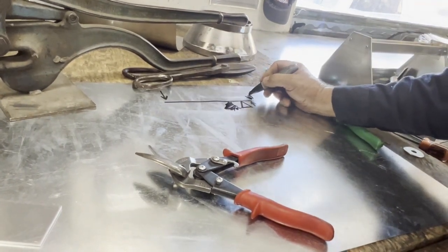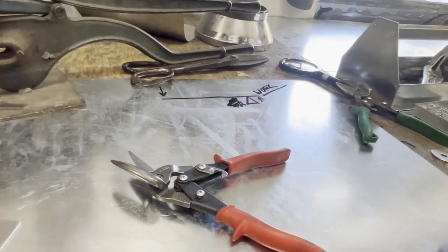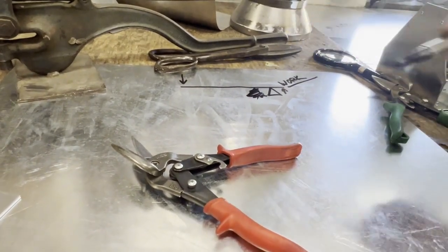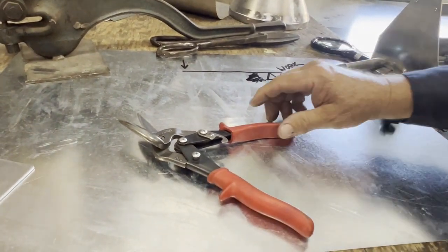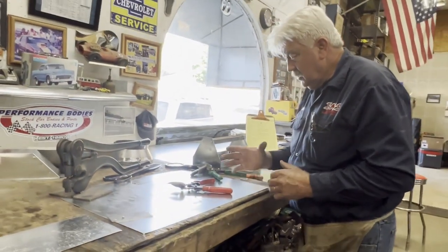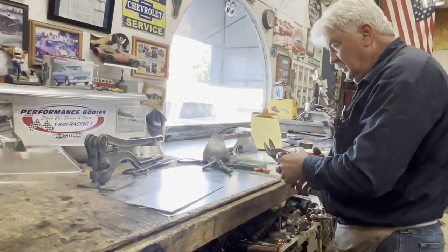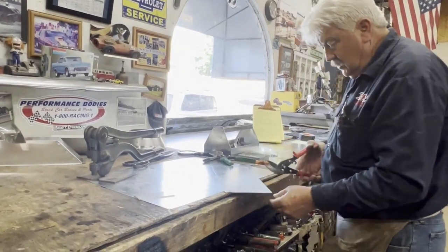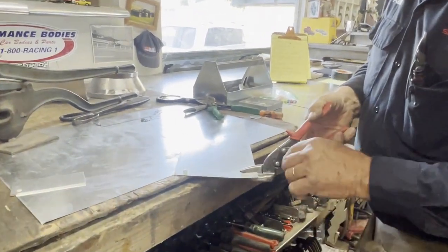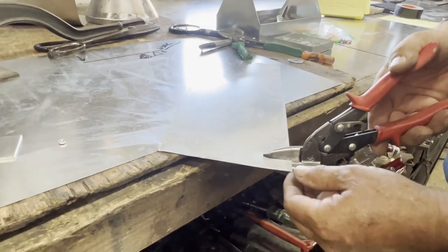The work is the metal. So this additional leverage allows us to do more work. As the metals get thicker, they get a little harder to cut. One of the things that we have to be aware of is that whenever we're cutting, whenever we're shearing, we always want to be mindful of which of these two pieces are we going to keep. Which one is our work and which one is the drop.